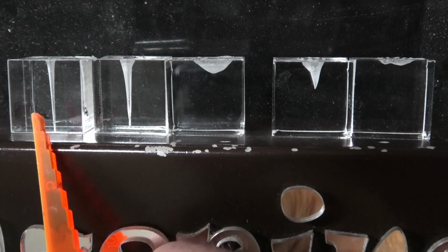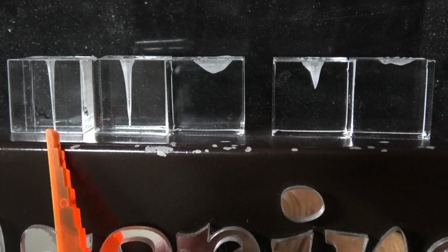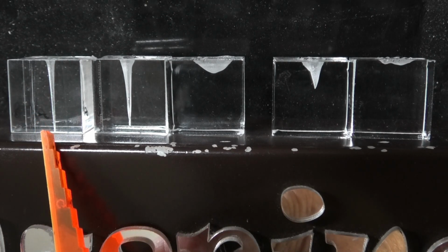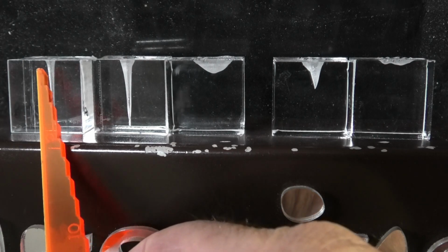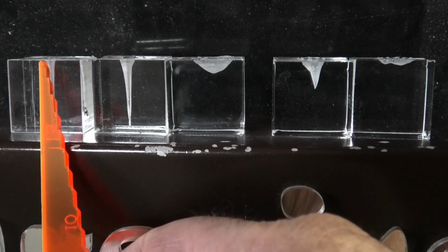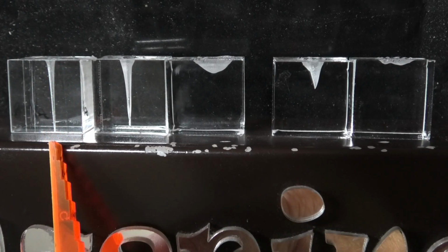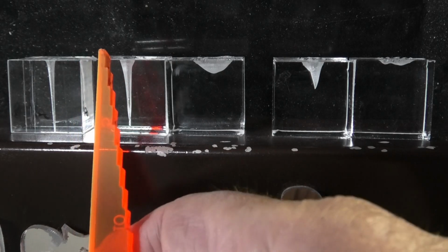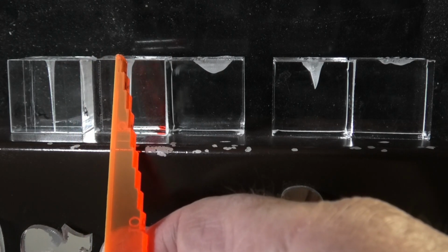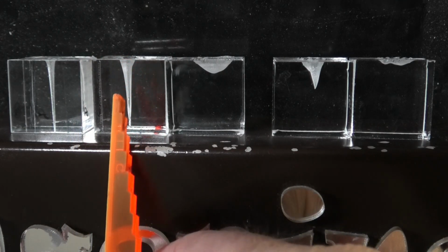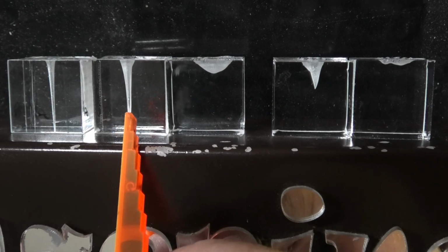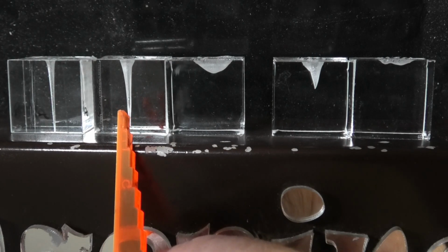Now, this is the beam as it exits the tube. It's claimed to be a 2mm diameter, and it's probably maybe 3mm diameter at the top there, but it did this damage in about 4 seconds. Here we're about 300mm beyond the tube, just after mirror 1, and we've already got some problems.